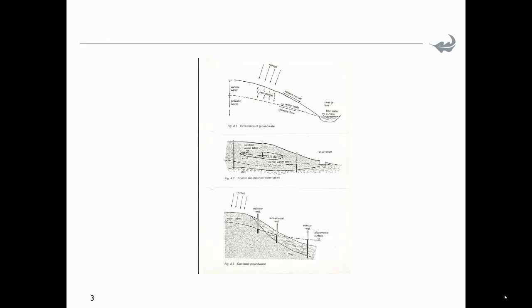So let's look at this picture. In the top picture, as the water precipitates from rain clouds, some of it flows down into the streams and rivers and eventually ends up in the ocean. Some water, however, seeps down into the water table. The surface of the water table is termed the phreatic surface and is at atmospheric pressure. On the picture you will see a little upside-down triangle at the water table. That is the internationally recognized symbol to indicate the water table.